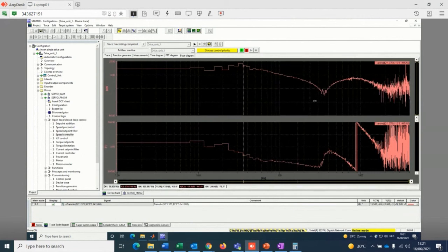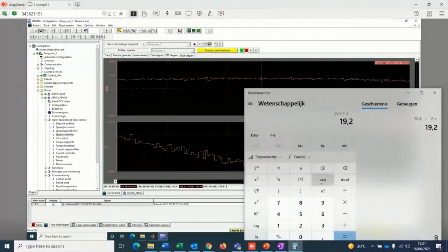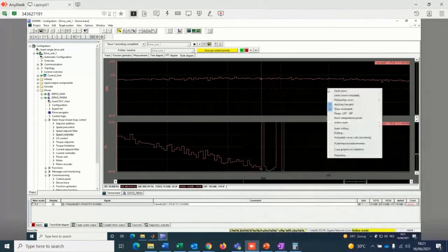We will go in the phase graph or curve to the first point in which we have the jump in the graph of the phase. So we can zoom in just by clicking here, holding the mouse. Then we will see that this is the value here. So in that value we have minus 5.8 decibels. So we take that value and we add 10, and then we end up with 4.2.